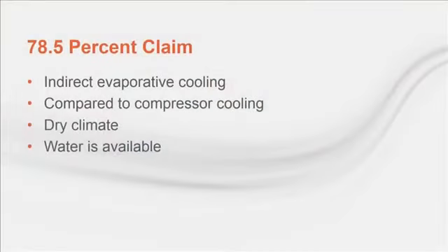Let's take that 78.5% claim. Now we compared indirect evaporative cooling with compressor cooling. If a project is in a dry location, water is available, and the right conditions are encountered, those savings are available. With that said, a project in the United States and east of the Rockies, or in the Caribbean, or somewhere like Malaysia, well, this technology probably isn't a good fit, and the stated savings won't be realized.